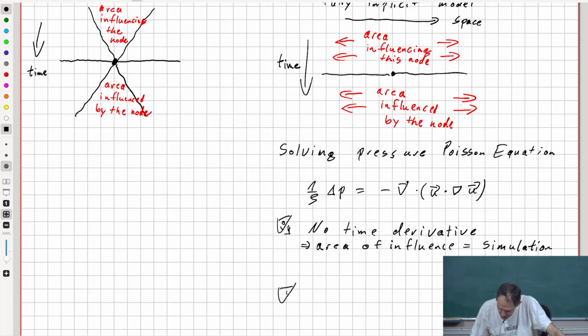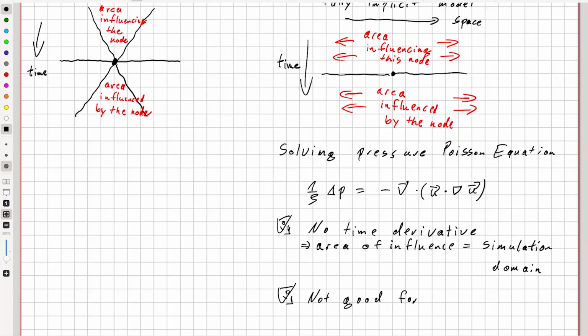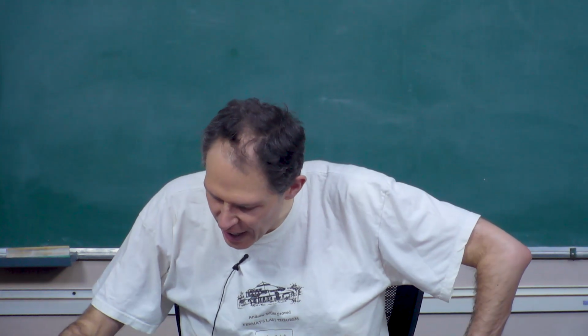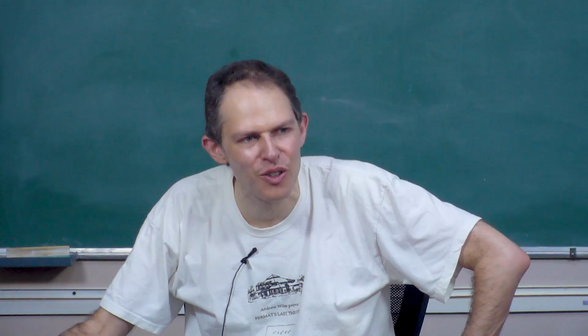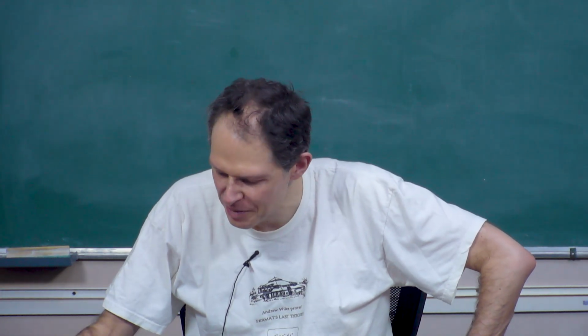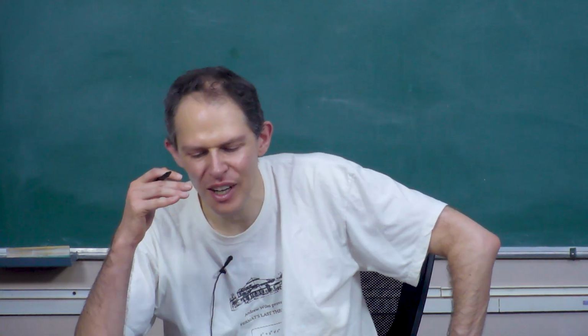And by the way, solving the Poisson equation is a problem of scaling. It can be pretty efficient to solve the Poisson equation, because the Poisson equation gives you real incompressibility, whereas when you use the lattice Boltzmann method, you get only some fake incompressibility, if you want. And sometimes this fake incompressibility can also cost you a lot of time dealing with it. But this is a scaling problem, so you have to think about this.